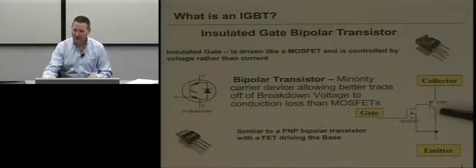So years ago we used to actually use these, more commonly the N-channel devices, and these would be the power transistor. One of the things you'll recall is that you have a junction drop here, so you got roughly a 0.7 volt from, it's actually the emitter of the PNP, but it's called the collector of the composite device. So how confusing is that, right?